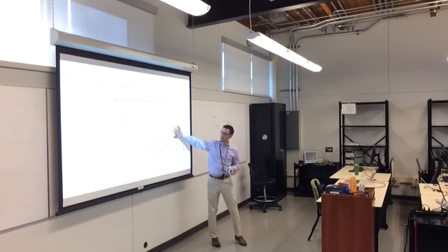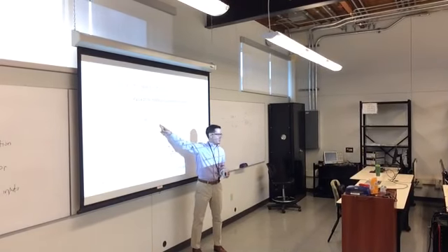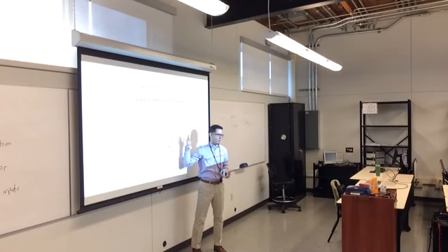What I need you to understand from this is that this value tells you when to go low. This value tells you how long to stay low. By setting these values, you can get a waveform of an arbitrary duty cycle.